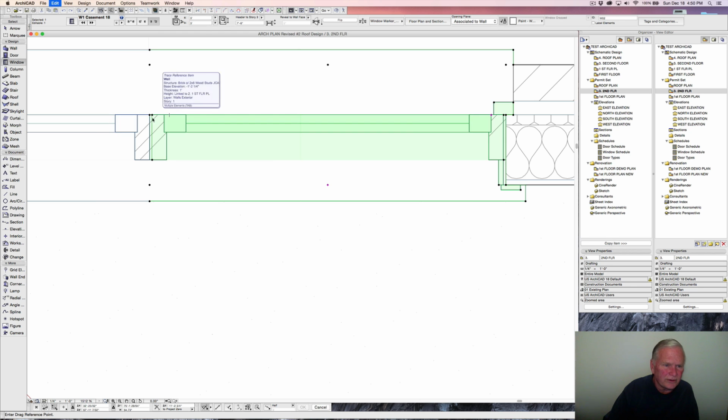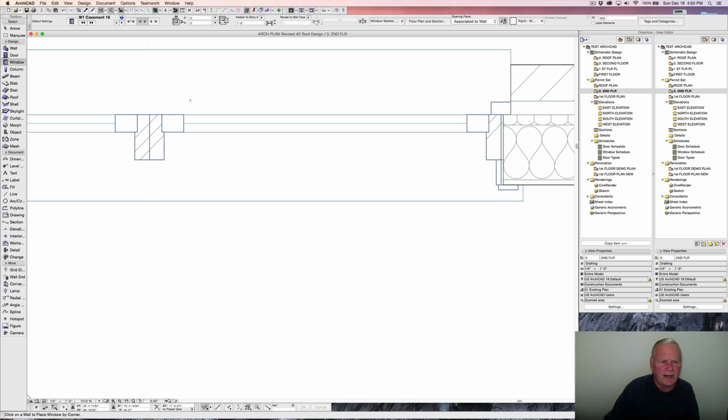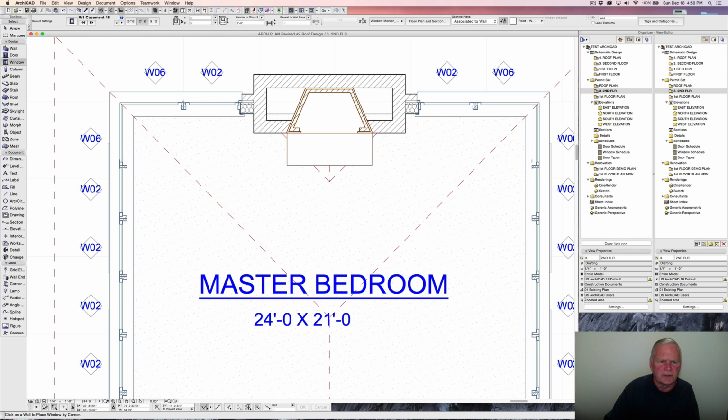And I didn't quite do that correctly, so I'm going to leave that there. And the reality is I may end up changing this to fatten this jamb up a little bit, because I think I'm going to have to end up with some kind of header cantilevering from here to here and catching another very long header that's going to come across here. Otherwise I've got this freewheeling corner here that's got to get supported somehow.